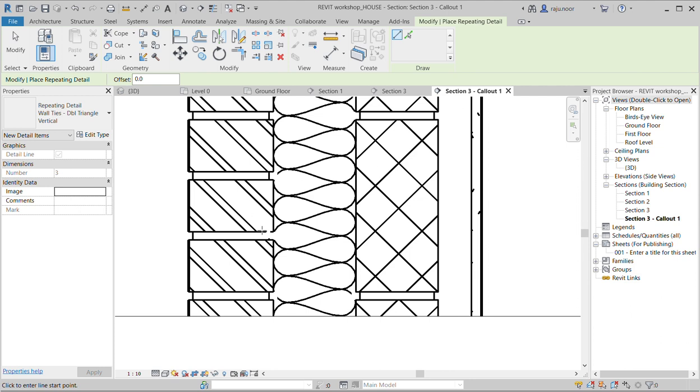Rather than two separate walls, so they both kind of become more rigid as a complete unit. So yeah, this wouldn't be one that would be used typically in a full fill insulation cavity wall. Typically, it would be maybe partial fill cavity walls, but we'll use it anyway. So yeah, we selected it. It's all set up in terms of the distances and that kind of stuff.